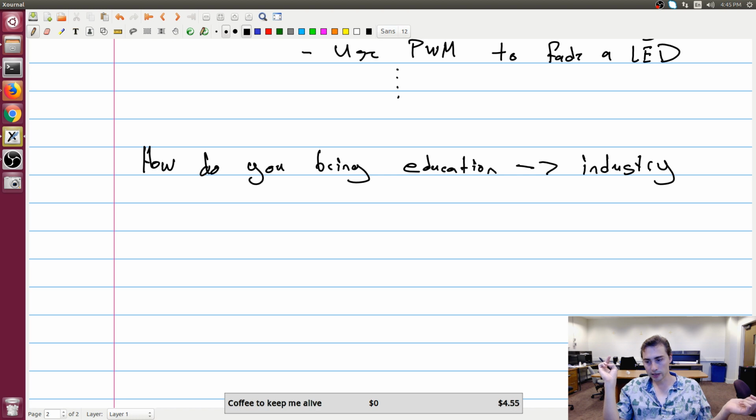When you try out a new design, do you model everything under the sun, or do you restrict what you experiment with? Yes, but you restrict what you experiment with in a realistic setting. In a GPU architecture simulator like GPGPU-Sim, you don't simulate the entire CPU and how it communicates with the GPU. You just instrument the instructions, or you just do all the CUDA API calls to the GPU and you simulate the instructions. But you don't simulate the entire CPU. You have to restrict what you experiment with, but you have to restrict it realistically.